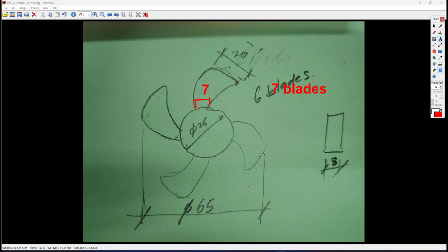Alright, actually there are a lot of ways to do this. If you look on YouTube at how they show you to model the fan blade, I found that the way shown there is they use sweep boss by using twist angle.